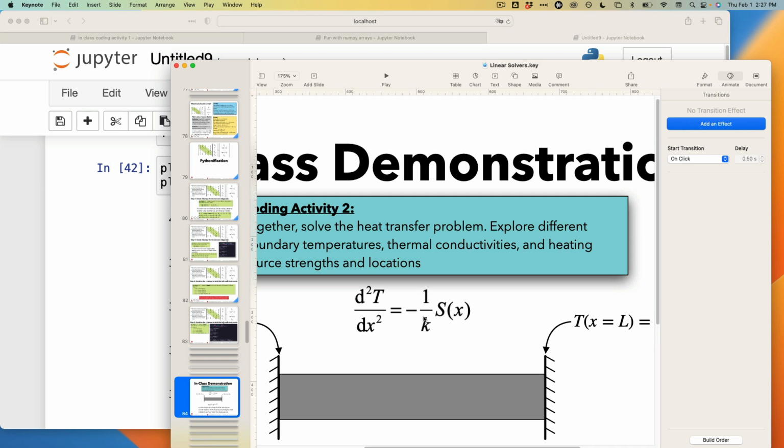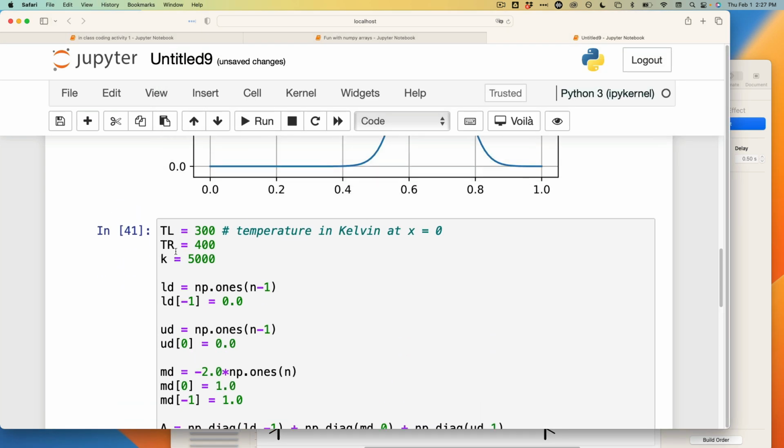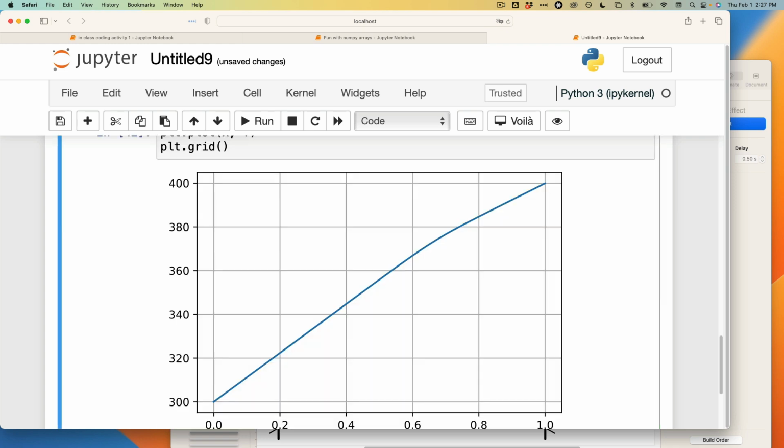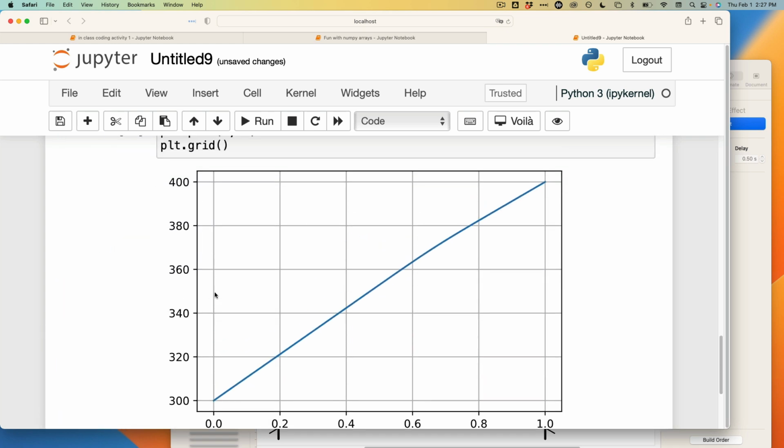As K approaches infinity, S over K goes to 0, right? Physically, all the heat that is being contributed by the flame is just spreading out very quickly. It's just going out sideways. It's just going out through the ends of the rod, through the two boundaries. So there's no room for it to peak out, right? So let's continue with this. Let's try a higher value, 10,000 maybe. Yeah, it becomes a straight line, indeed.